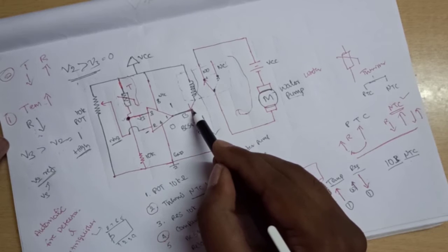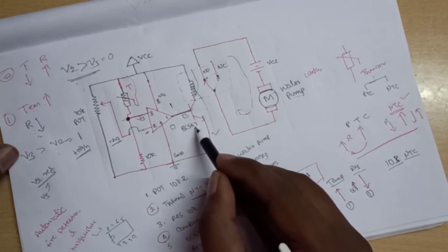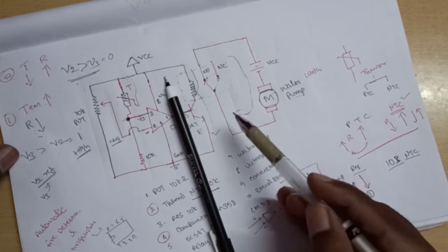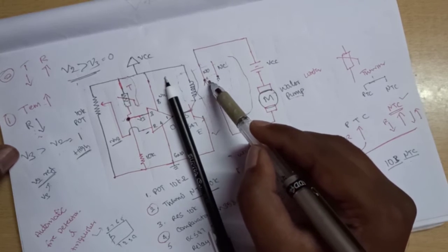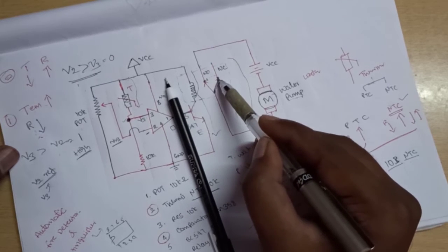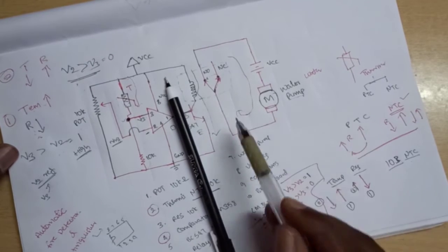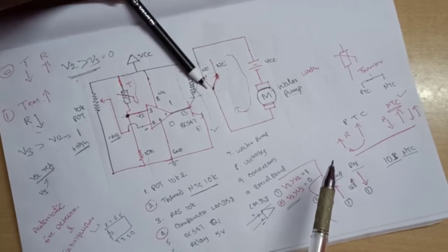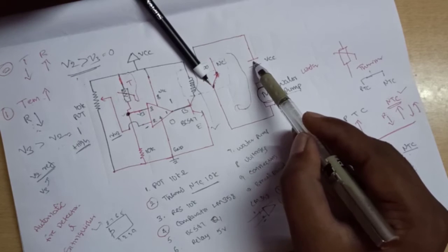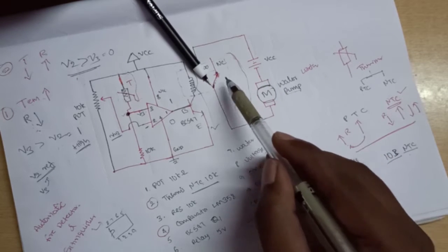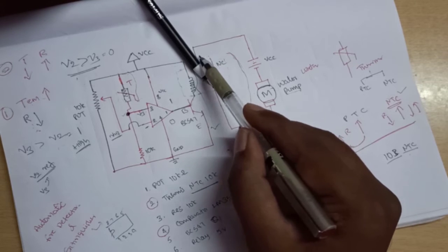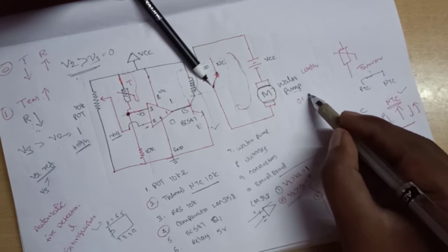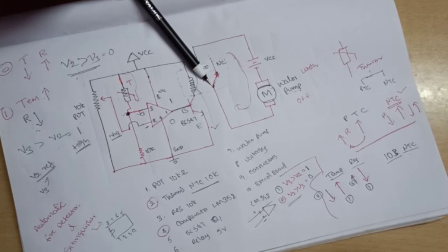So that transistor will be in the off condition. Off means this is the open circuit. Now 0 volts, so the transistor will be in the off condition. Hence this pole will be returned back to the normally closed contact. So the pole connected here is an open circuit. It looks like this. The battery is connected and there is no closed circuit, it is an open circuit because it is not connected. Hence this water pump will be in the off condition, there is no water on the fire.